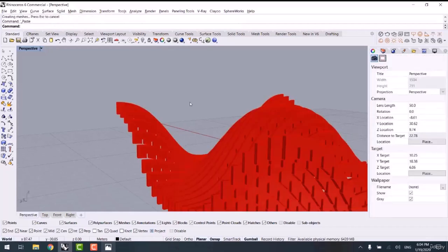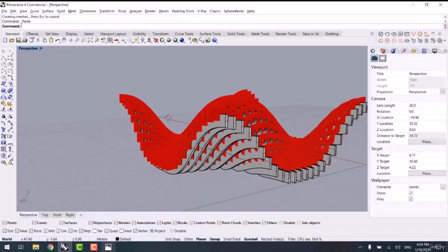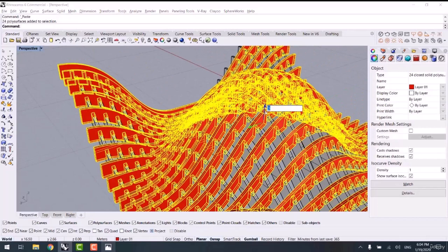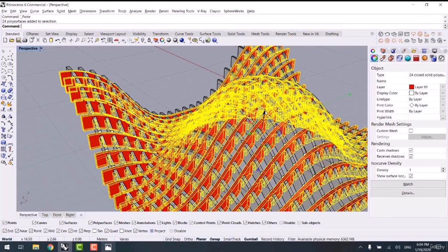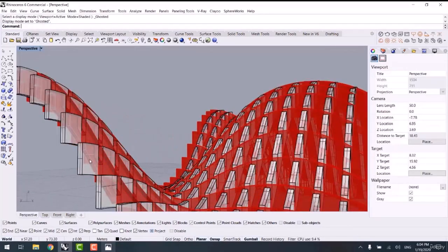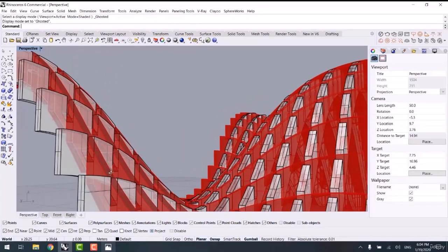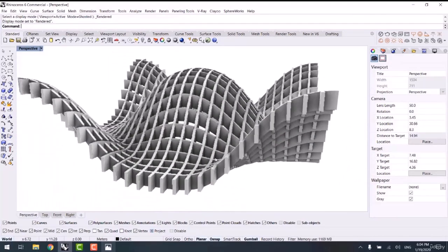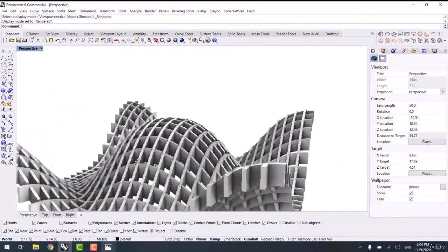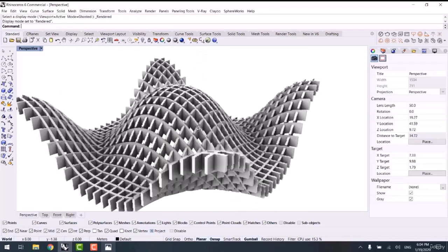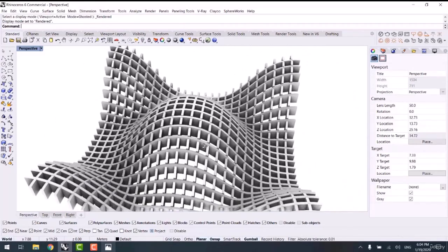Check this out, and then Ctrl V to paste the previous result which we had copied, and then here we select it, and then we want to move it downwards at minus 0.5 meter this way. Check it out, they are well organized and neat, and the two surfaces are matching with each other here at the rendered viewport by using Softmove, Boolean difference, and contour and other commands.